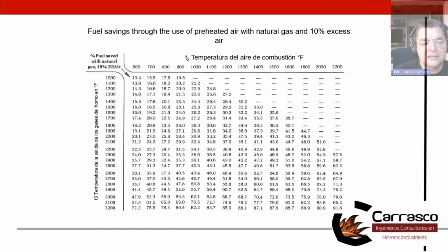There are also software tools where you can enter information about the furnace, the process, the temperature of the process, the actual fuel, the heat capacity of the fuel, and the altitude of the system is also something to consider, because you are almost at sea level, and I am living at 2,200 meters above sea level. So the available oxygen in the air is different here than it is down there at sea level.